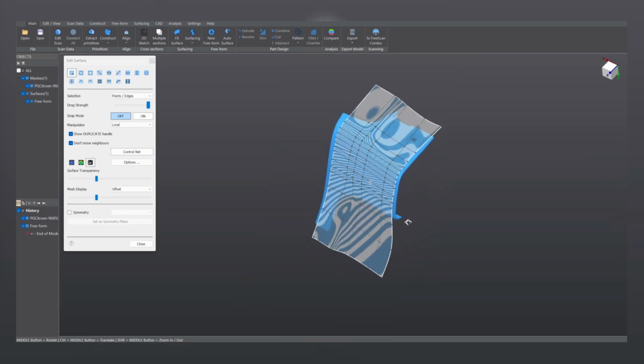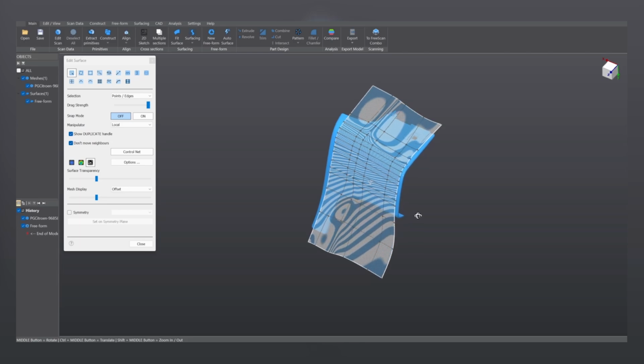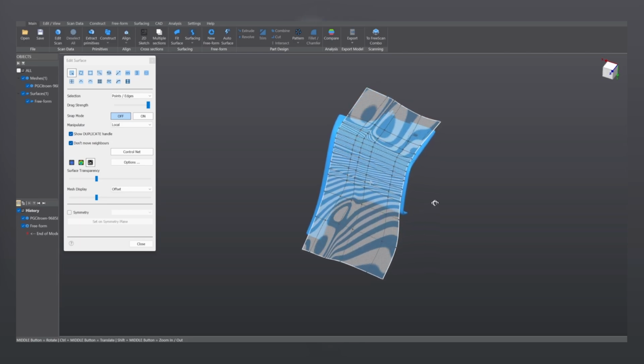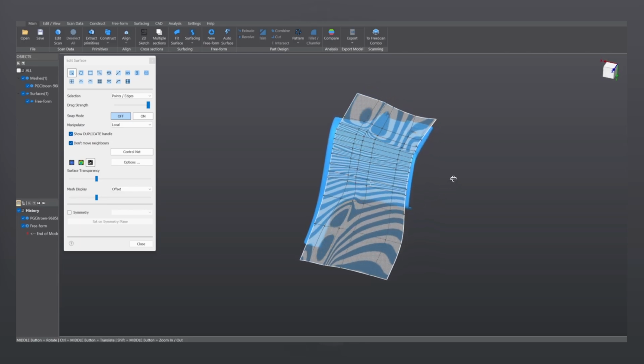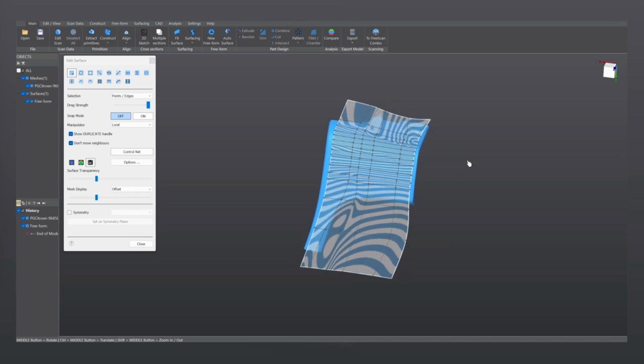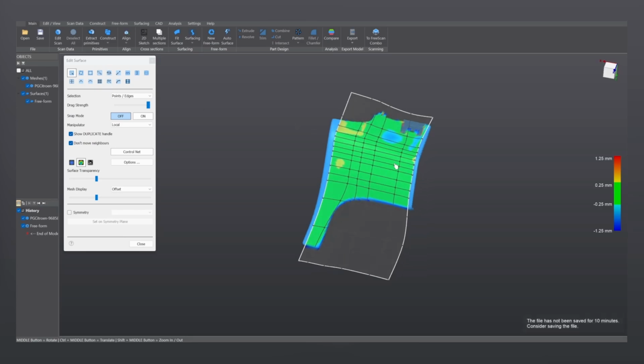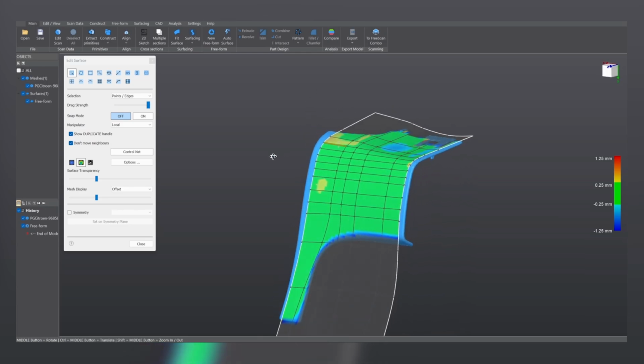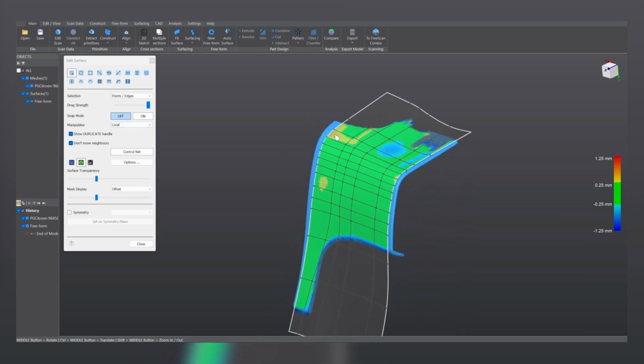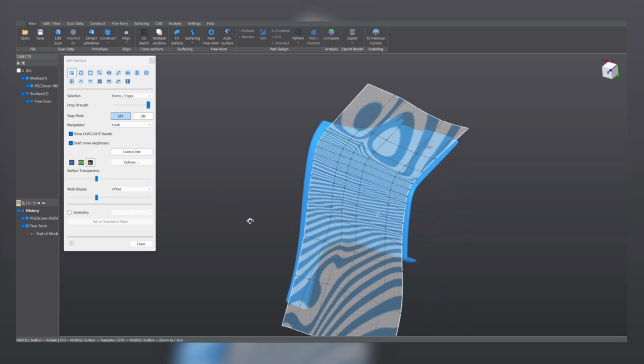with the zebra stripes. And what we have to pay attention to here is that these zebra stripes move smoothly onto the surface. And to improve it, what we can do is giving it some clicks here on the smooth tool, and by compromising the smoothness, well, not the smoothness, but the tolerance a little bit, we obtain a better surface quality.